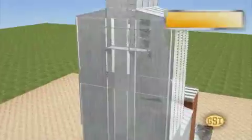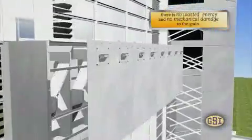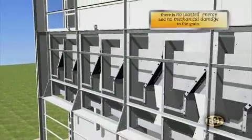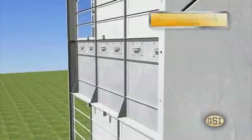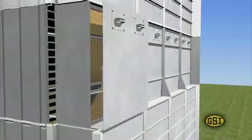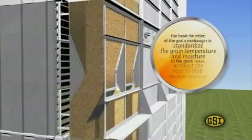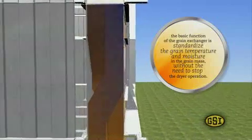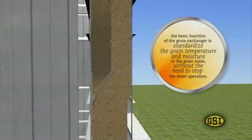At the end of the first stage of drying, grain inverters move the grain within the column to ensure even drying. The inverter is made from smooth sheet metal, which enables the grain mass to rest for a few minutes during drying to homogenize moisture and temperature.